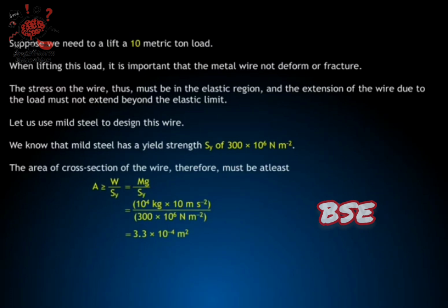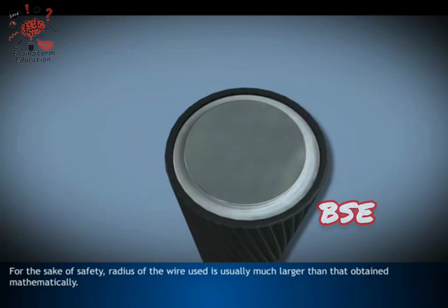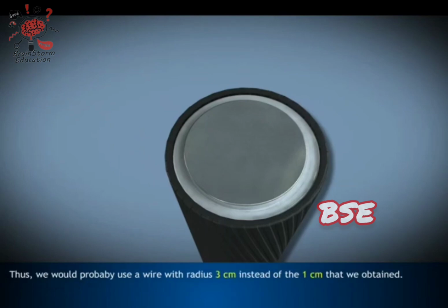This is further equal to 10^4 kilograms into 10 meter per second square, whole divided by 300 into 10^6 Newton per meter square. This is finally equal to 3.3 × 10^-4 meter square. This is equivalent to a wire of circular cross-section with radius of 1 centimeter. For the sake of safety, the radius of the wire used is usually much larger than that obtained mathematically. Thus, we would probably use a wire with radius 3 centimeters instead of the 1 centimeter that we obtained.